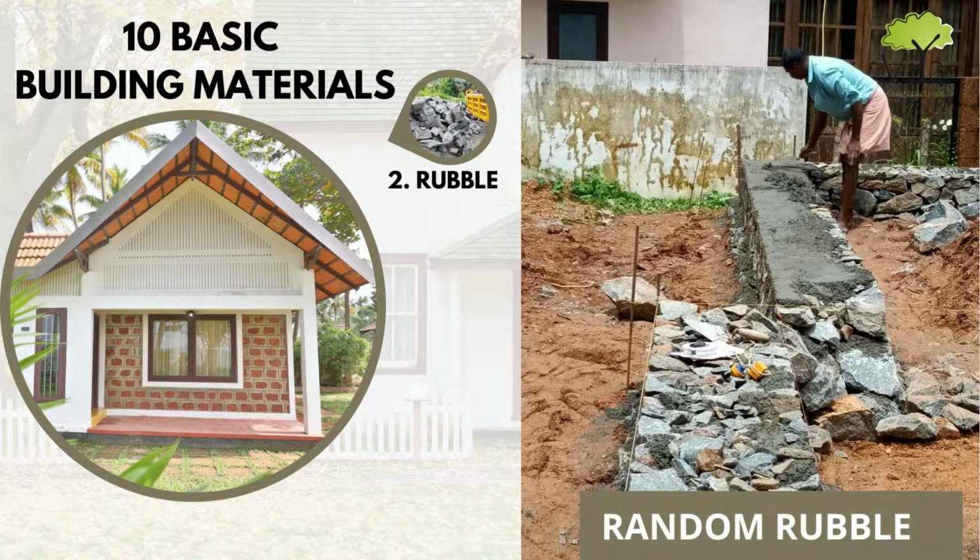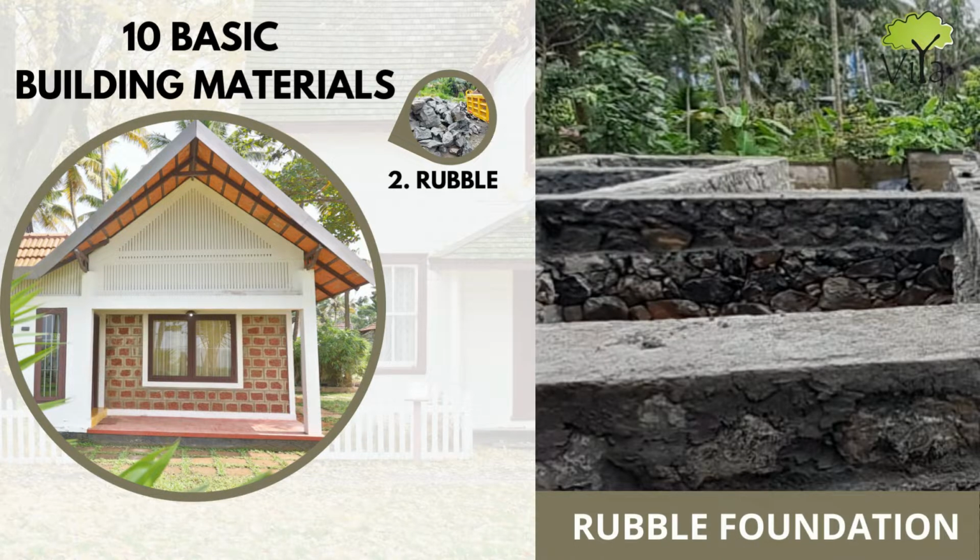In the next stage, the rubbles are packed together just as in dry rubble, but the only difference is that the stones are held together with mortar. This is called random rubble and this layer rests above the soil. A layer of mortar separates the dry rubble and the random rubble.